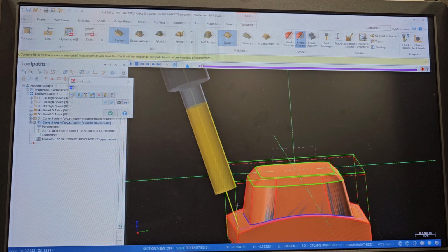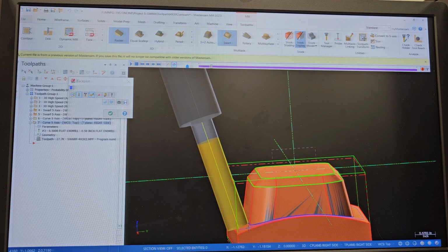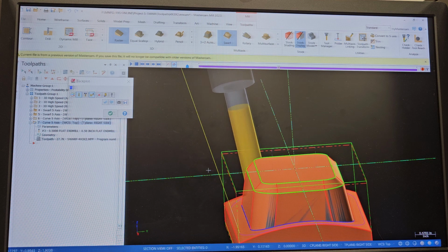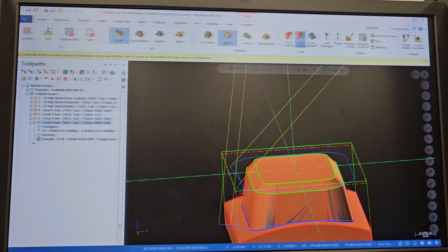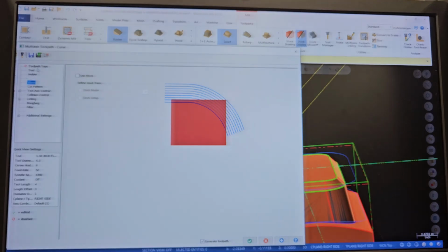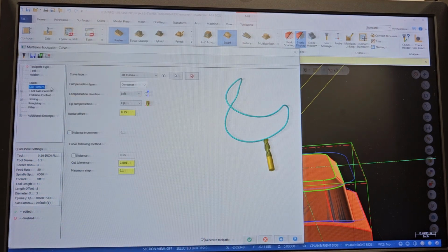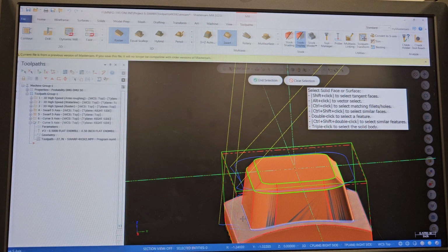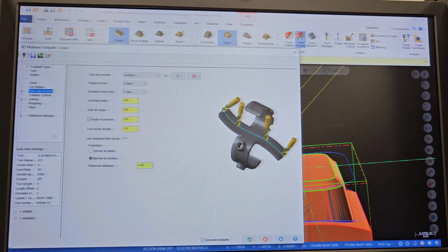It's gonna stay to the left, but your tool axis is gonna be controlled by the surface, that's why it's good, but keep that surface in mind. And here, tool axis control is gonna be controlled to the surface, and that surface is gonna be this surface right here. The one you select right here, that's gonna be that surface. So just one curve toolpath, I have done two, we don't need to, just one twice.